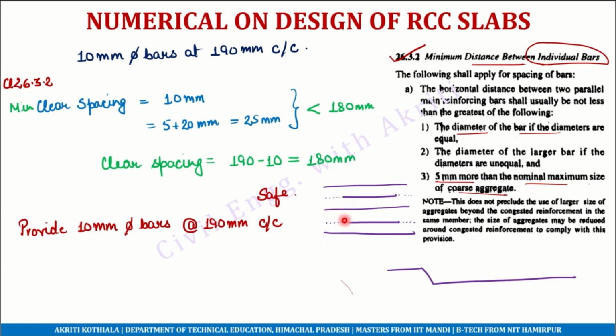It is simply to cater to the negative bending moment which might be introduced in the slab during the course of its life. What this simply means is that whenever we are providing positive reinforcement, or the reinforcement which we've just mentioned above, we are providing it for this type of bending moment.